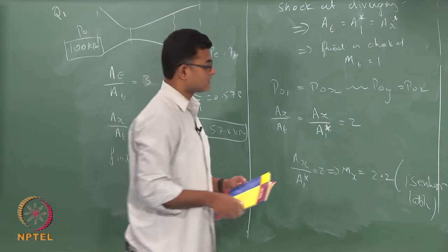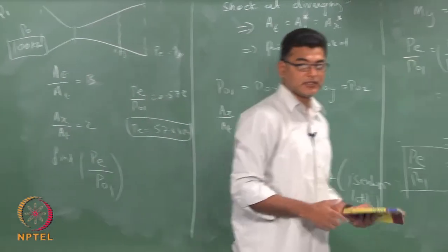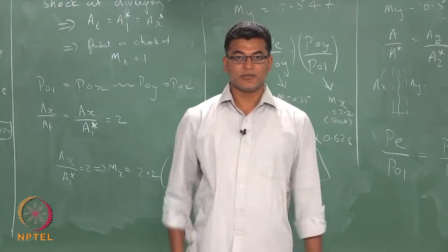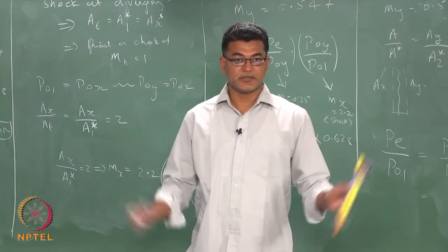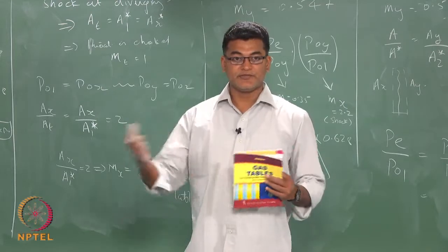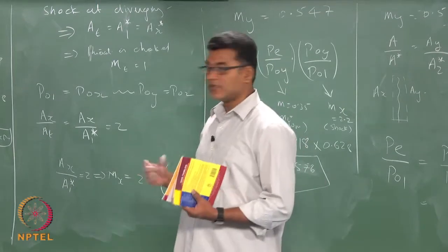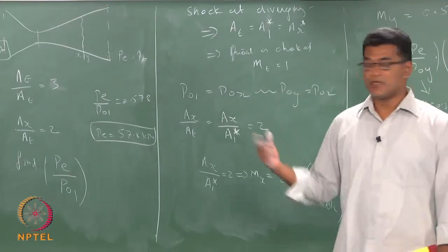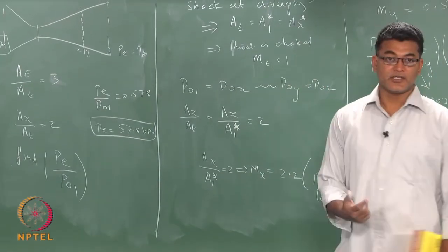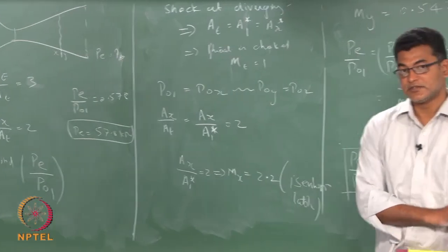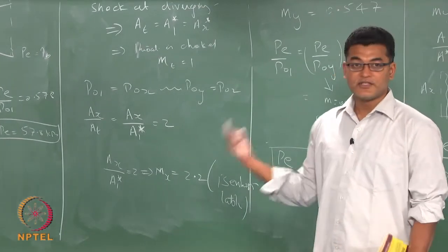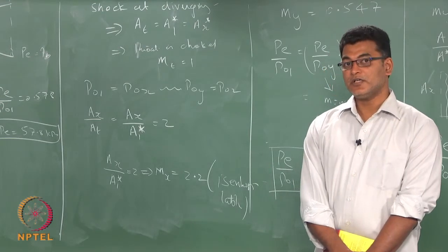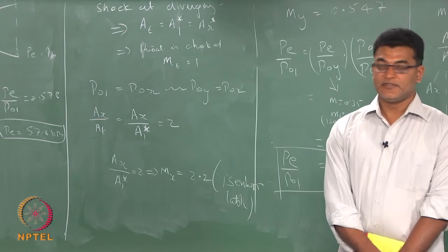So the key is you consider the shock as the non-isentropic process, everywhere else it is an isentropic process, whatever be the case before and after. If I have a long duct, you do not need the CD nozzle information, where the choking condition or throat condition is not there, but if it is a nozzle you have these conditions. The same is true for a diverging diffuser.